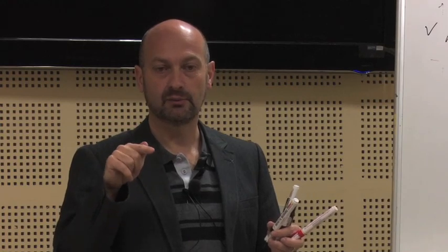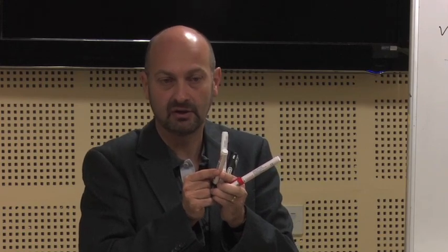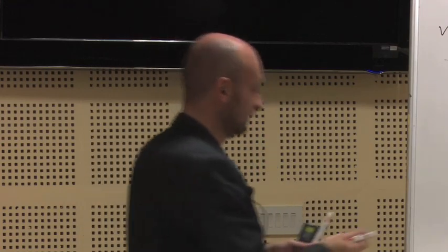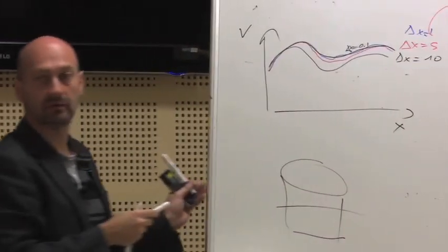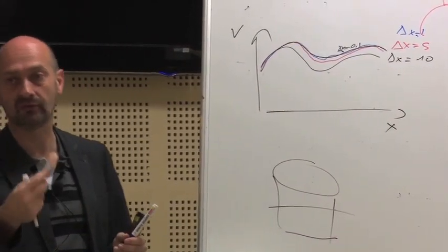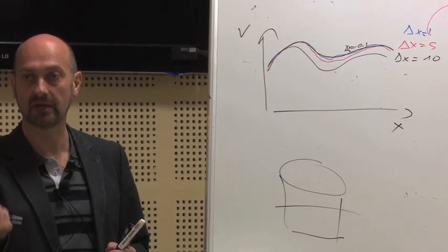Because you have to keep in mind that CFD is providing you a discrete solution of continuous equations. So we expect that as the mesh becomes finer and finer, it should approach a continuous solution. So this is usually what we do. But of course, when you go from there to there, you have divided the mesh size by 100, probably in the three directions. So that is 100 times more time consuming.